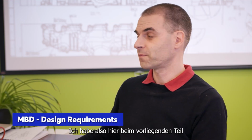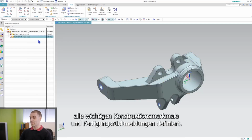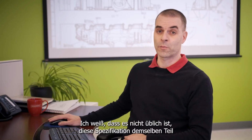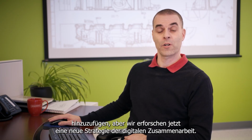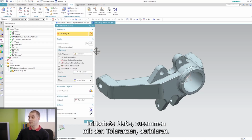Typically, once the 3D design of a part is completed, the next step is to proceed with the model-based definition. To do so, I have here a derived part where all the key design characteristics and manufacturing feedback will be defined. I know it's not common practice to add this specification to the same part, but we are exploring a new collaborative strategy. Now, using native tools, I will define the most critical dimensions along with their tolerances.